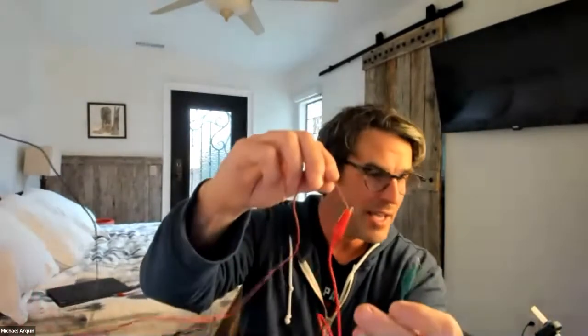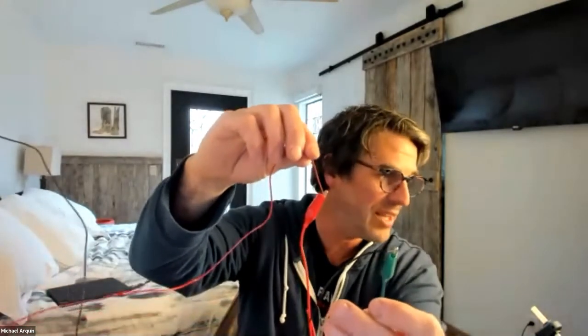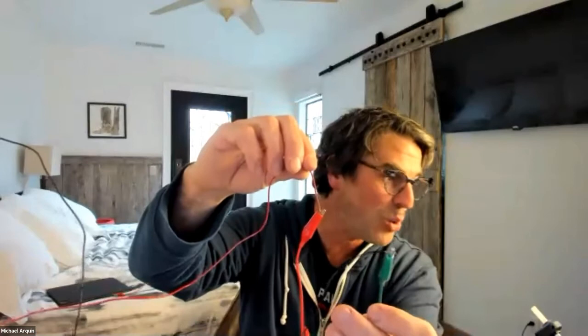But right now, the way I have it hooked up, each wire is just connected, and I'm measuring the voltage between the two wires, okay? There's no load on this turbine right now. Basically, it's just free spinning. There's no load. It's not having to do any work, okay? The reason we give you a resistor is it then forces this turbine to do work.